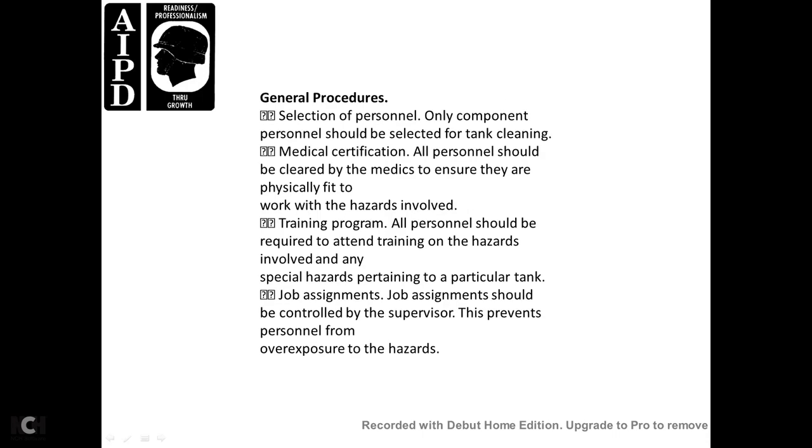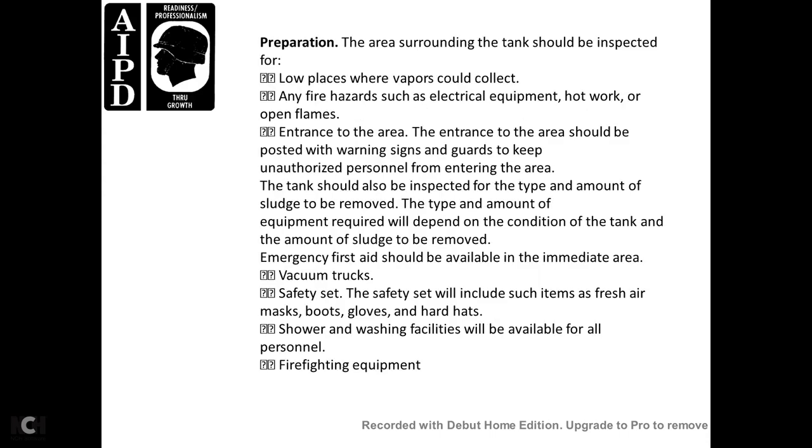General procedure, selection of personnel: only competent personnel with tank cleaning experience should be selected, and personnel should have medical certification and be cleared by medics to ensure they are physically fit to work with the hazards involved. Training program: all personnel should be required to attend training on the hazards involved, including any special hazards pertaining to the particular tank. Job assignments should be controlled by the supervisor to prevent personnel exposure to the hazard.